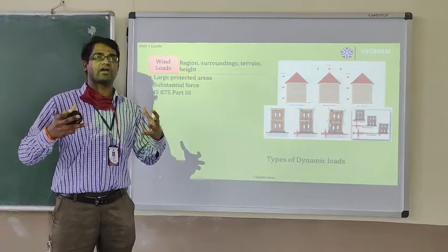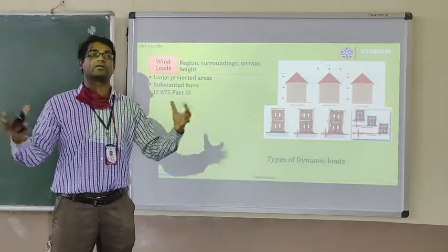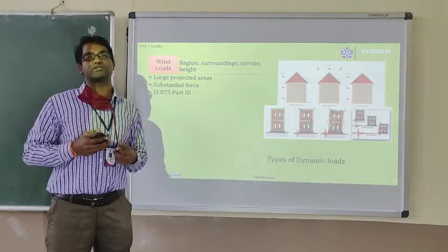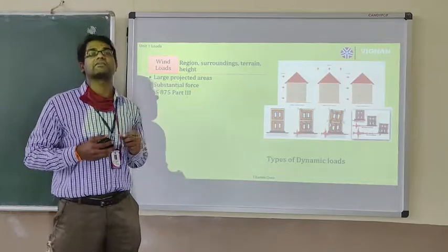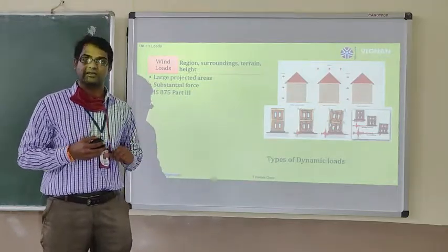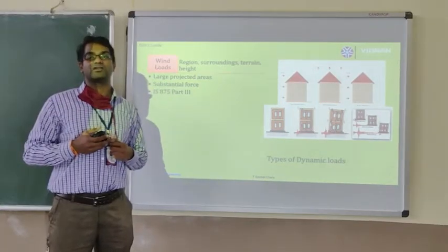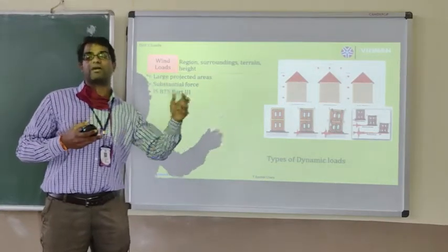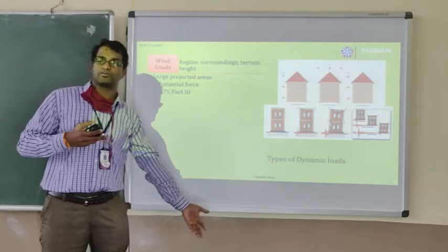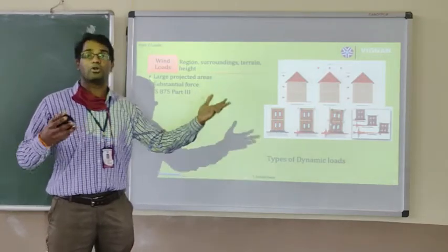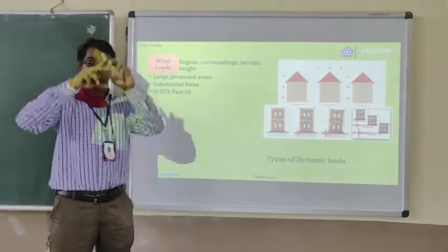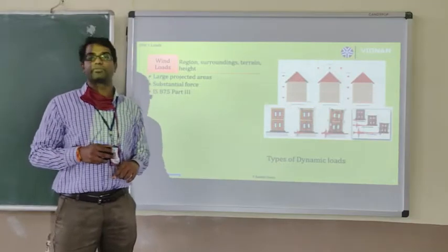When you have a huge building, wind load is a major load, which we discussed in the previous slide when it came to instability. Your bridge is very long and you did not consider the lateral wind load, and that became instability and complete failure. That can happen to a building also if you are not considering the projected area of your building.